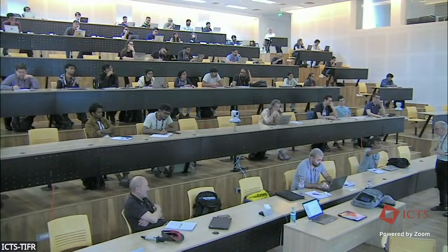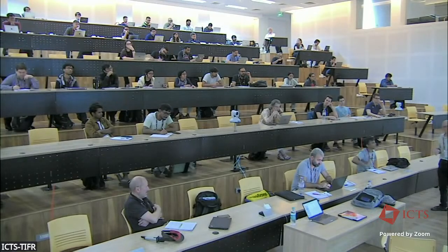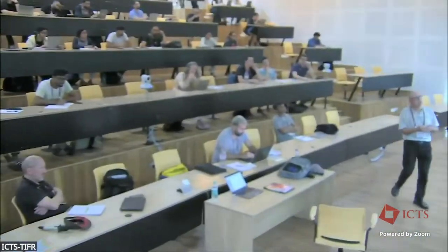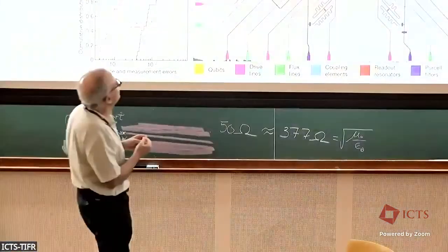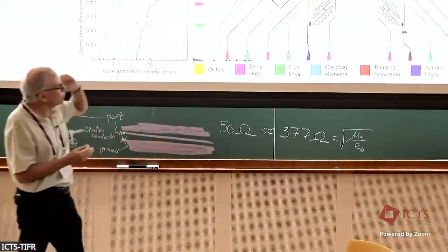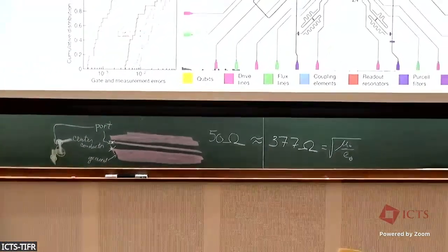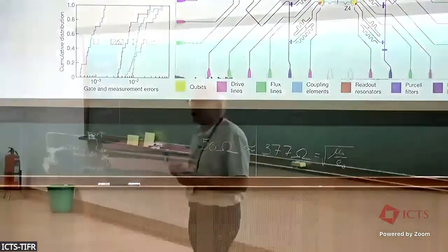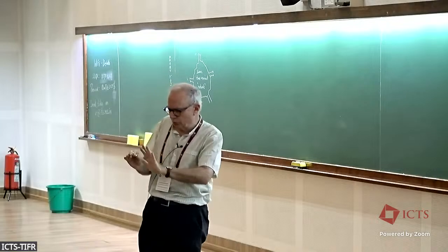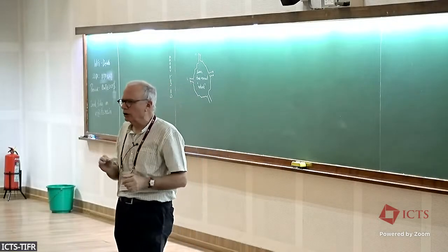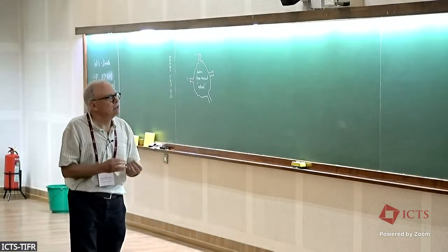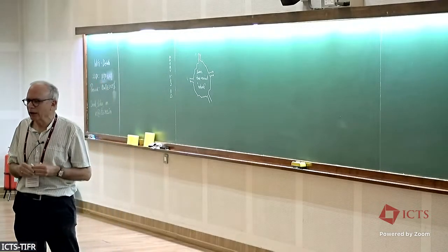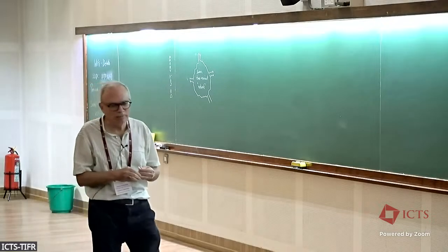The channels are kind of waveguides? Almost everything is waveguides in this picture. Let's see if there are any exceptions at all. This stuff interior to the qubit is not entirely just waveguides. There are other shapes of metal. These star-shaped things are, again, a plate of metal of the shape of this star, and that will affect details in the sense that it affects the electromagnetics, although not that deeply.